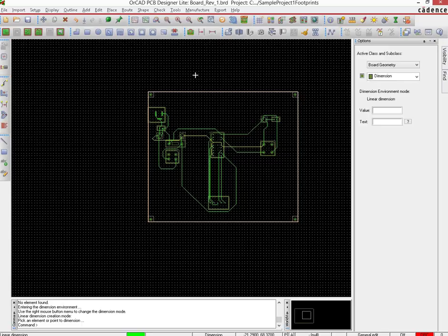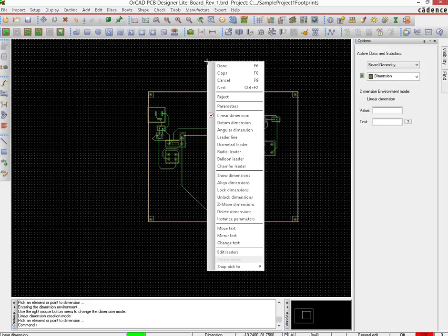And stuff like that. So to do that, what we do is we use the dimension edit tool, and that is right here. So we click on it. Once we click on the dimension edit button and it gets selected, we should verify by right clicking that we are using the linear dimension. If we are not, then click on the linear dimension and it will get selected.